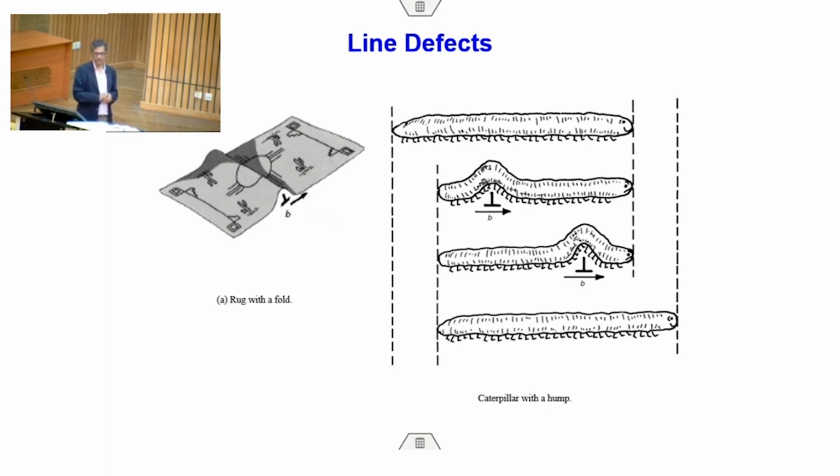That is what is known as a ruck, or a fold. Okay. So a dislocation is exactly like that. A dislocation exists inside the material, and if you apply a shear force, it moves through the material. That is what happens. This can also be compared to the motion of a caterpillar. If you look at this caterpillar, and now you want it to move from here to here, it could jump, but it does not actually jump. Caterpillars are very smart.